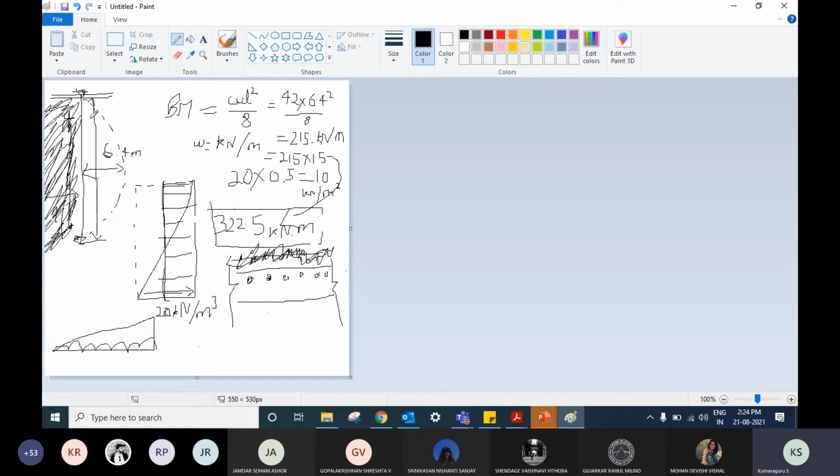It is not facing any tension, because only from one side the soil is there. So on the tension side we need to design for the demand, and the other side could be minimal reinforcement. Now the question was finding this thickness and the reinforcement diameter and spacing. That's it. Once you do that, the other things you can put minimal reinforcement.